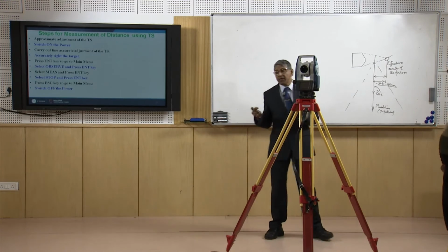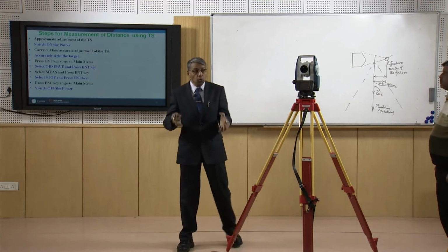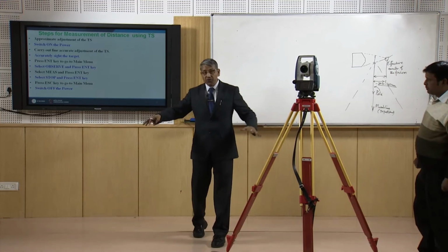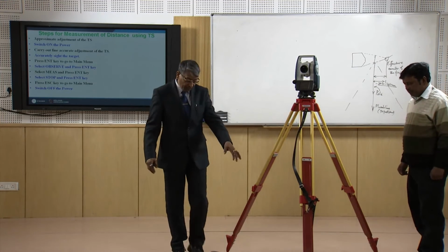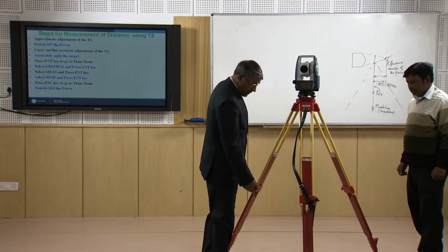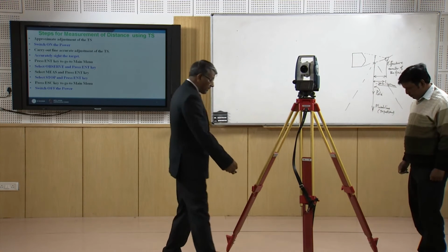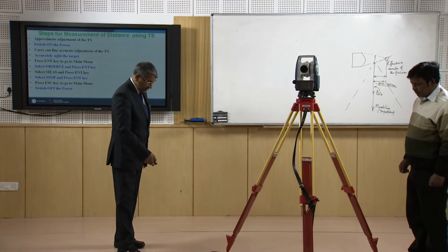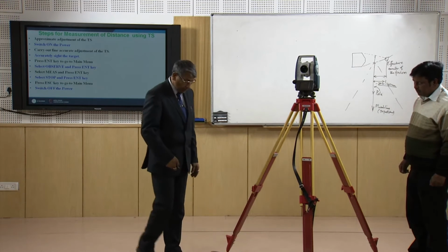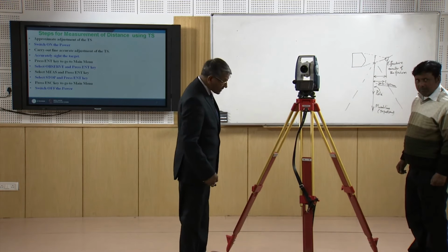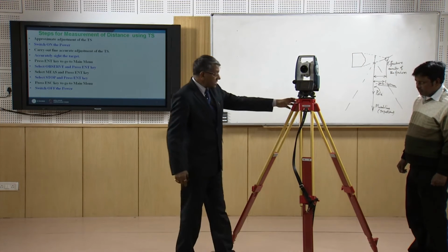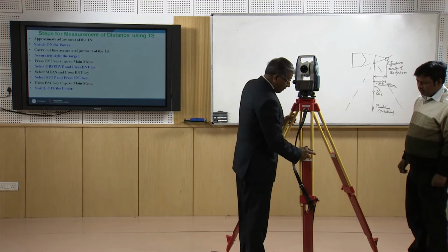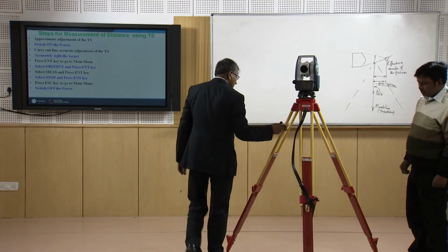Many times we are bound to use our instrument on a hard surface in the field. In those cases also we should prefer to have a frame like this. This frame will not cost much, but it is an attitude we have to develop, and if we set up our instrument like this, the chance of it getting damaged will be much less.